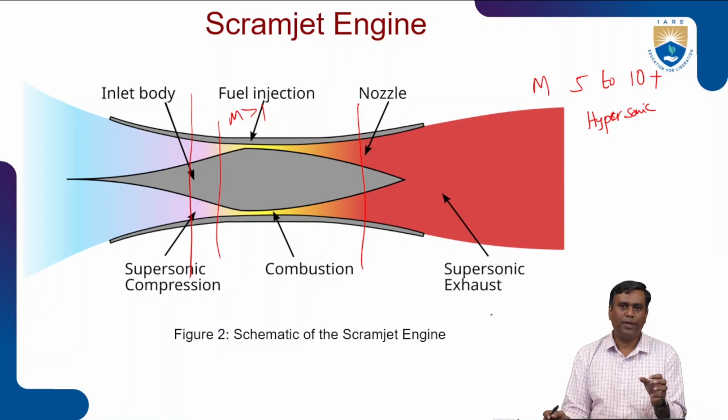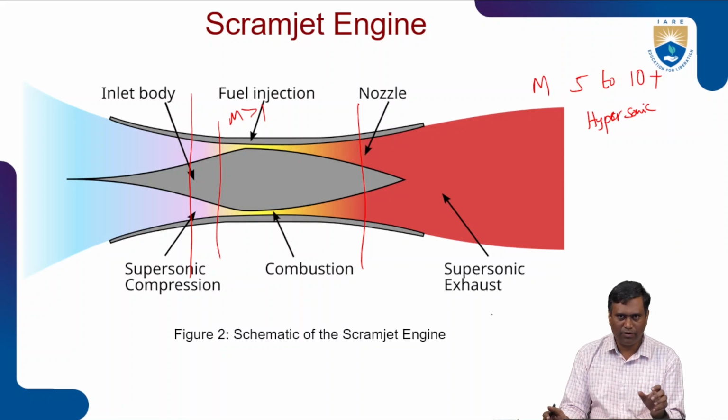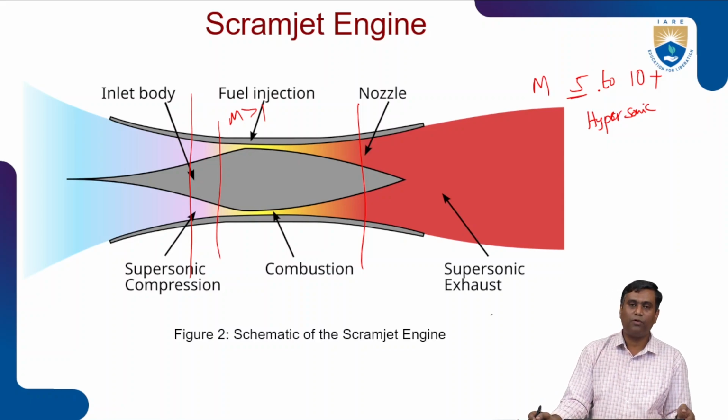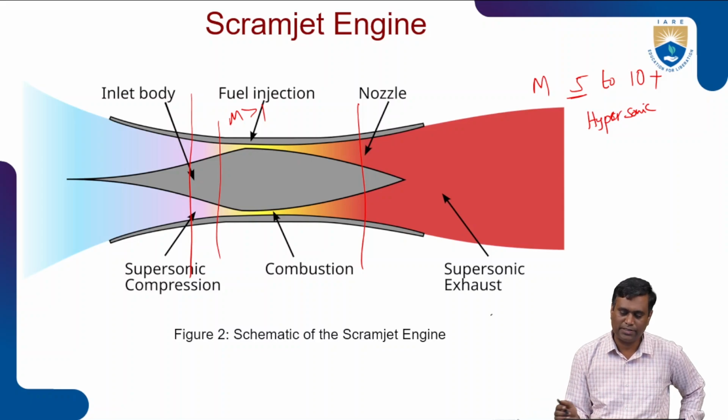Hypersonic. So minimum, in both the cases, minimum supersonic speed is required. In this scramjet case, this can work efficiently only at greater speeds, like more than 4.5 or above 5, right? 5 to 10 plus. At such hypersonic speeds, only this scramjet can work effectively and efficiently.